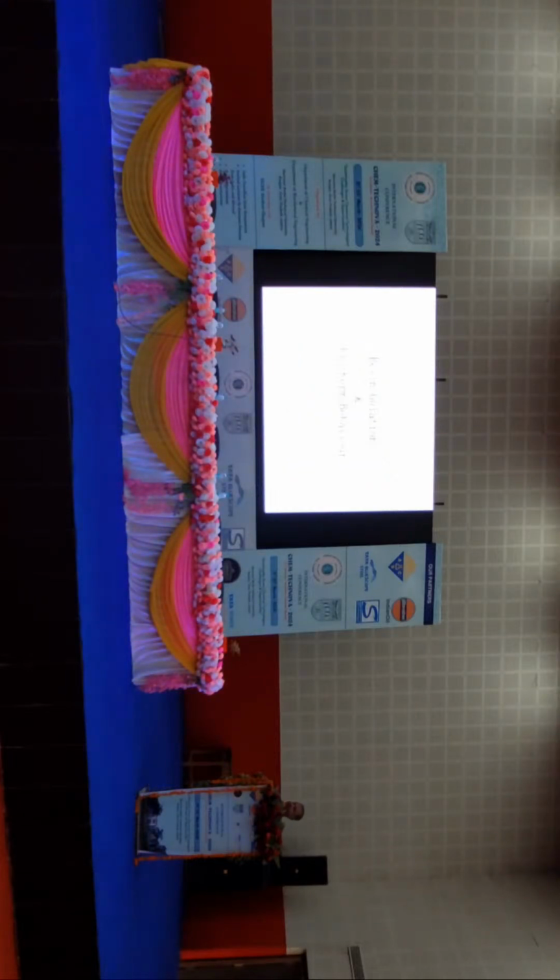Next one, please. As I told earlier, when resin undergoes curing, there will be exothermic heat. That exotherm behavior also has to be studied. In this case, we have followed ASTM standard D2471, and 100 ml of resin is taken, which is a medium reactive isothermally unsaturated polyester resin, and we use curing aids such as accelerator and catalyst.